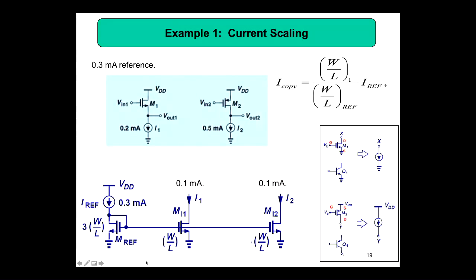So then what we will do is make a current source. The current source we already made using NMOS, so you can see two current sources. Then we are going to make a current mirror. Here is your golden current coming from the band gap reference, 0.3 milliamps. You are using this current mirror configuration with two NMOS, because you need one NMOS for the source follower and one NMOS for the common source stage.